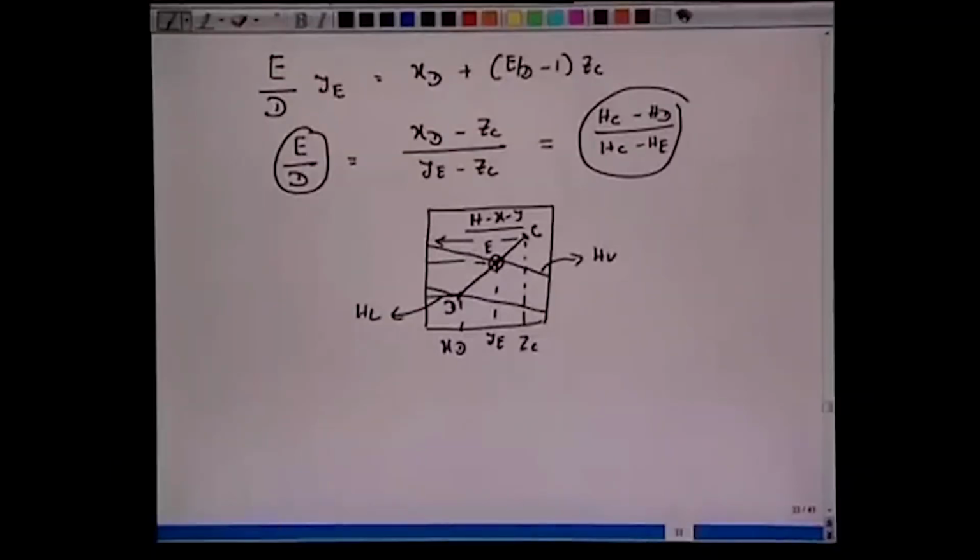So when we want to do distillation, separation in a single stage operation, vaporizer or flash drum, what is generally the practice? You take a fluid, heat it, bring it to a saturated temperature, and it should be pressurized at high pressure, so that you can throttle it and flash it to vapor and liquid. Then you will see a separation in XY. So it's a single stage. If we understand this, and draw it on our TXY and HXY diagrams, then when we take up the larger distillation column with different stages, trays, this will act as a building block. So let's start with this single stage operation or single stage vaporizer, which is nothing but flash vaporization.